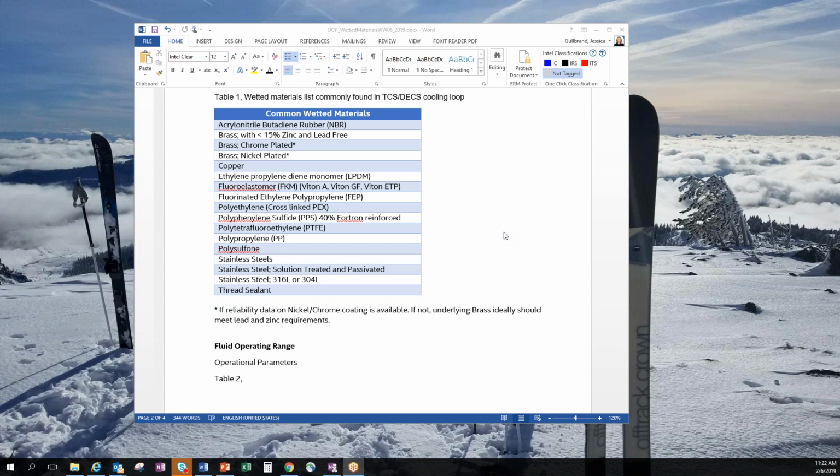Any other comments? This is Steve Harrington from Chilldyne. One comment is that if you hook up a system which has anti-corrosion additive A into a system that's filled with anti-corrosion additive B, what happens? Or do you have to drain any subsystem before you hook it up? The other thing that we run into is the anti-corrosion additive people don't tell you what's in them, except in cryptic MSDSs, and some of them are toxic to fish. If you have a supercomputer with lots of fluid and you dump it all down the drain, you might cause an environmental disaster of some sort. So that's another thing to keep in mind.